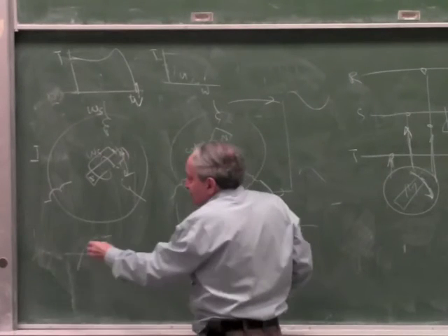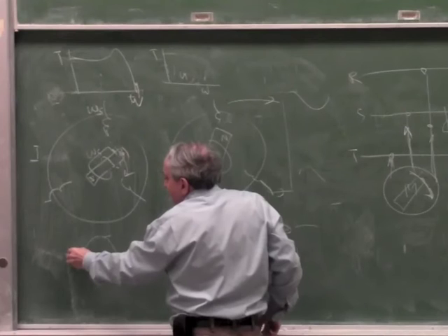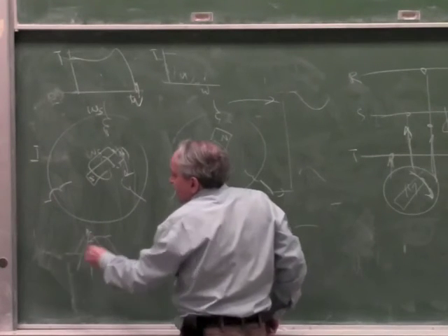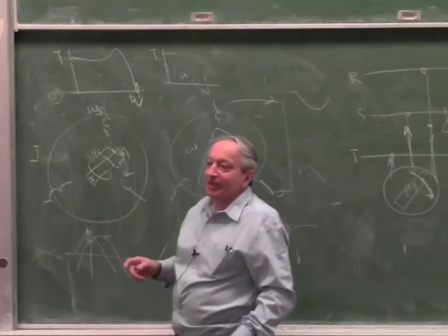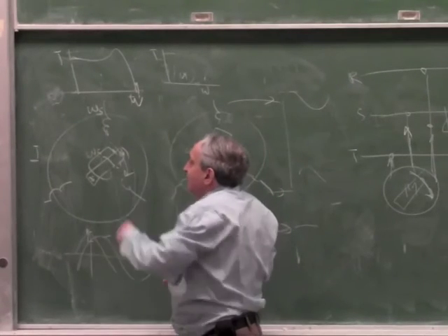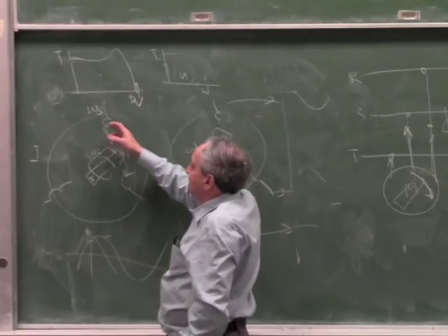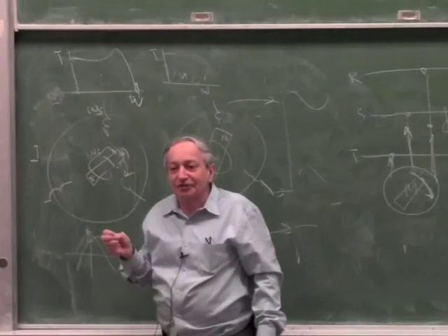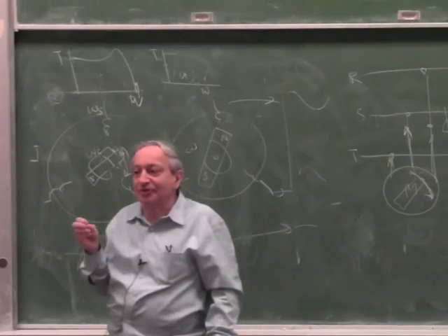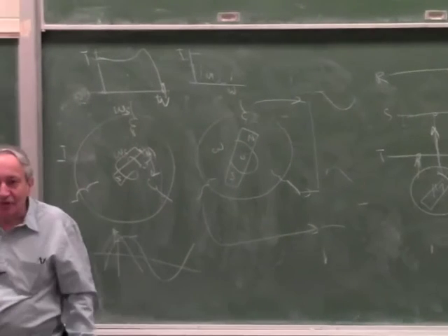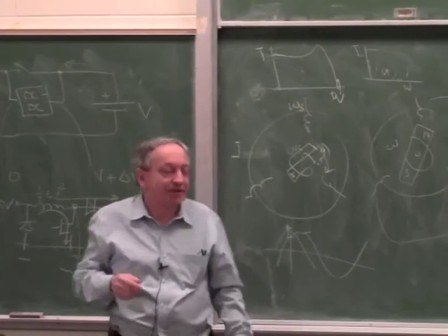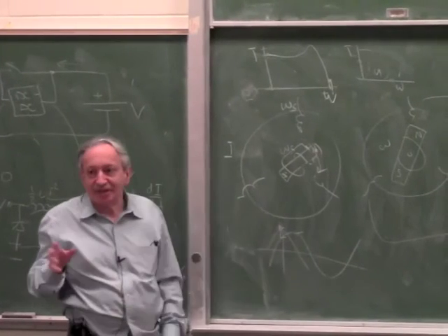It's only higher because its phase advanced, like this. So momentarily, it will actually feed the power back. So if you continuously feed it, so that this EMF is at the right phase and higher voltage, power will flow back. So even in an induction motor, if you overdrive it mechanically, it can feed power back. And that's how it's done in electric cars. That's how the Tesla works.